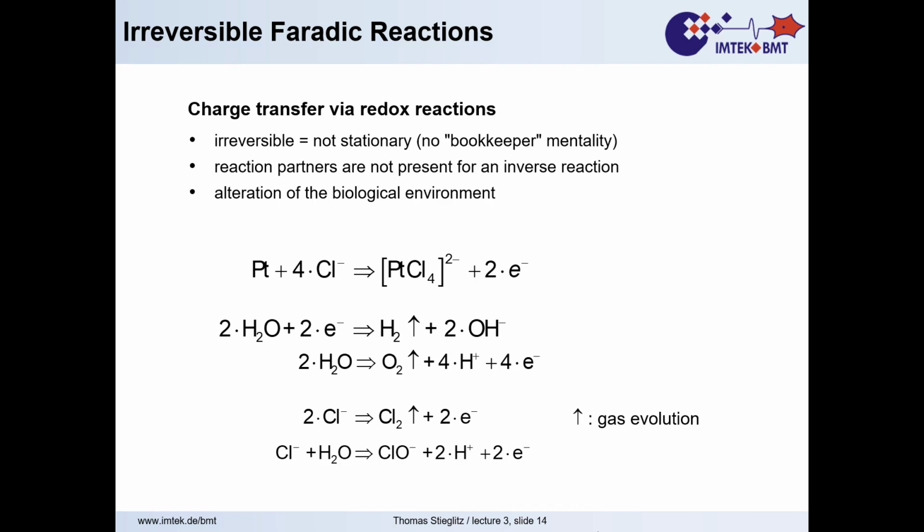The nasty thing that we get in corrosion if we use platinum as one of the electrode materials for implantable electrodes is that we can get platinum tetrachloride, and if we have those biphasic charge pulses, it's a tricky process. It doesn't go back and forth, but we get platinum tetrachloride, and that settles down on the electrode surface and, like dust particles, creates a rougher surface.